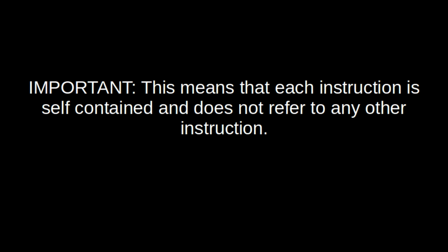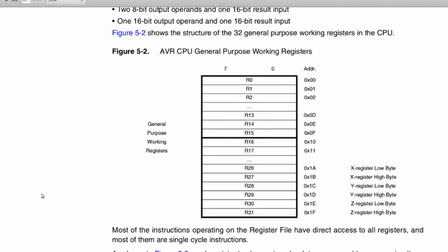So, how is it that programs string commands together to accomplish anything? How can you do it? The microcontroller has a part of its memory set aside to store temporary data called registers. Registers are just like any other memory location in SRAM, except that the instruction set refers directly to those memory locations. There are several different types of registers. There are 8-bit registers, pairs of 8-bit registers that are meant to be used to hold 16-bit values, but you can use them as separate 8-bit registers. And there are certain registers where each bit has a defined meaning. And there is a collection of registers set aside to be used as a stack.